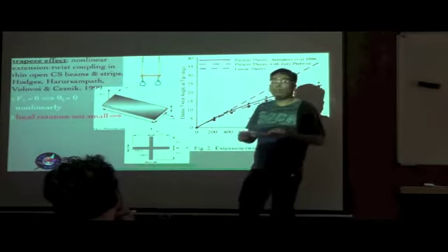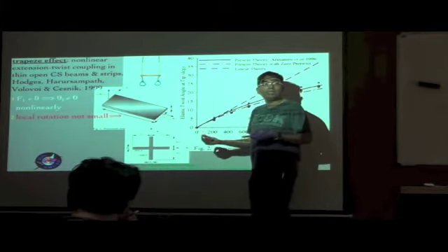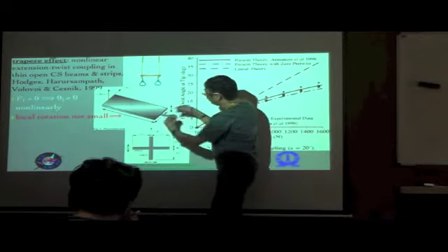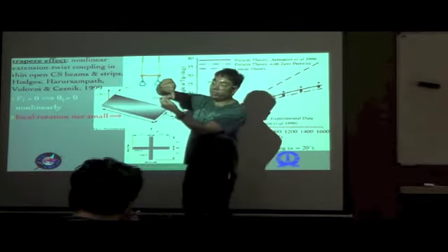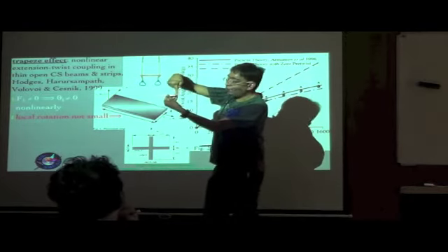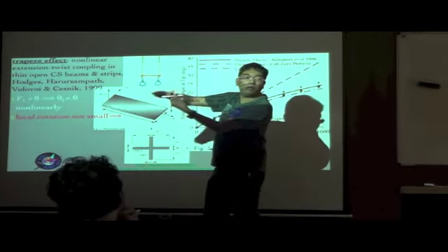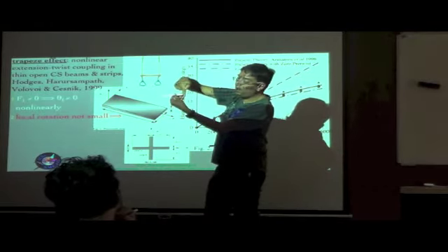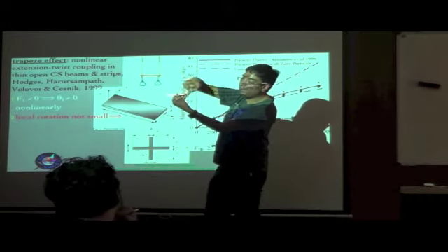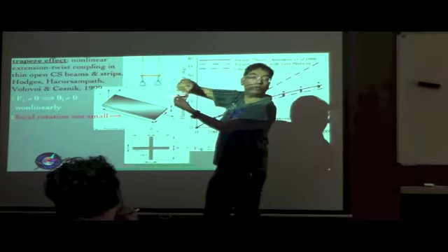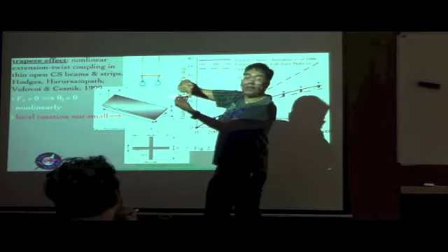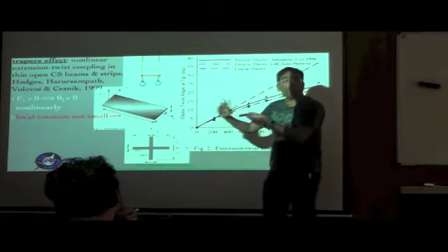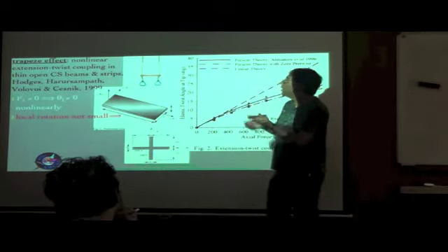And that out of plane warping predominantly exhibits itself as what is known as a local rotation, and that particular rotation is in this thin strip. If you take an element like this, which is perpendicular to the plane of the strip, if you think of it as a plate, that particular normal line element rotates like this, and it rotates differently at different locations along the width of the beam, and that is what is causing such a large nonlinear coupling between the extension and twist.